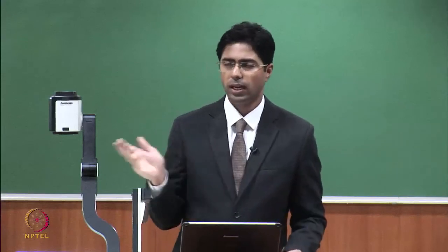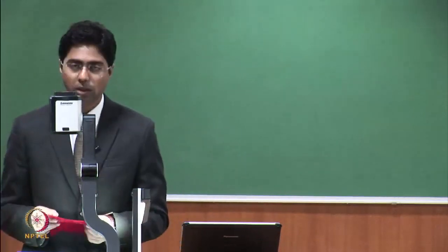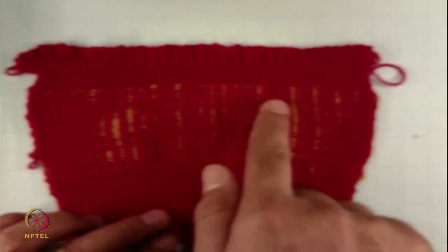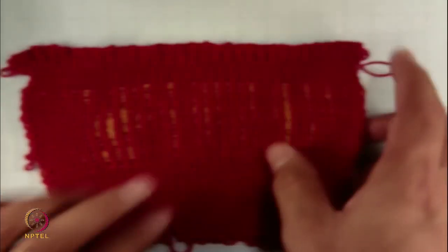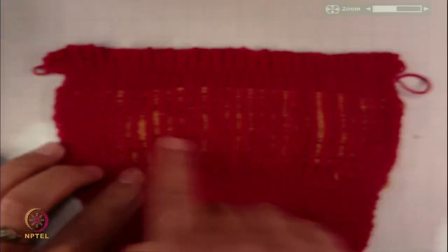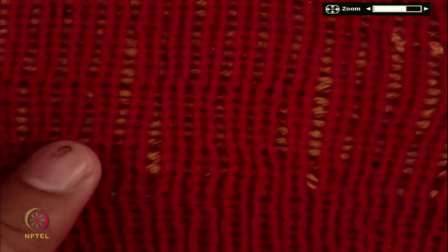will be floating. So, I have these fabric samples with me. You can see here how the yarns will be floating, although I have not used elastomeric yarn, but I have used another yarn. You can see the other yarn is hidden between the technical front and back loops. If you see from one side, this is a simple rib structure, and you can see in the courses how the yarn is locked. So, this yellow one is not part of the loop, it is not intermeshing, but still it is locked inside the structure.